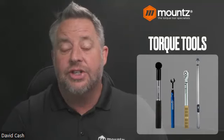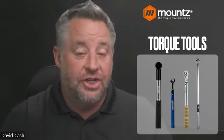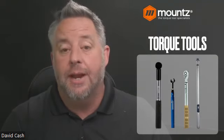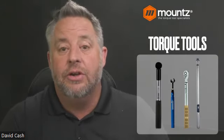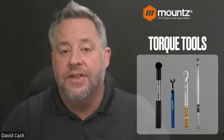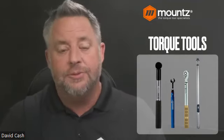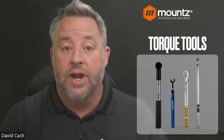Now, the next wrench within the torque wrench family there is going to be a digital style wrench. And these typically will use some type of sensor to be able to tell you once you've hit a certain value. But just like the click wrench, there is nothing to prevent the operator or the user to go past the actual value that's being used, unlike the cam over or breakover style wrench.